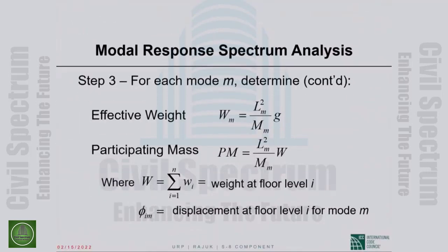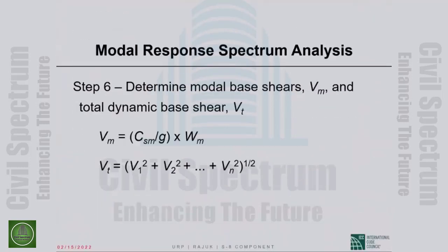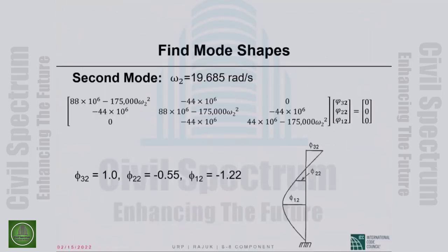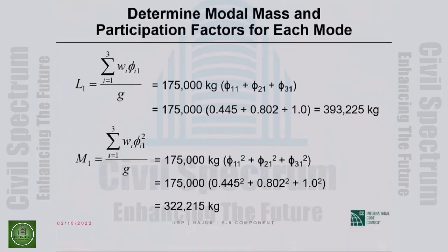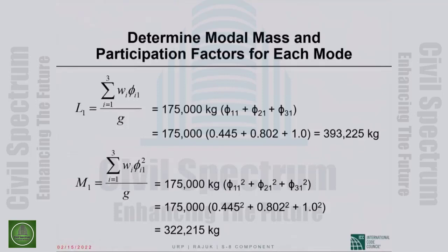Then effective weight and participating mass. So once we have our mode shapes, we will calculate the L and the M for each of our 3 modes.